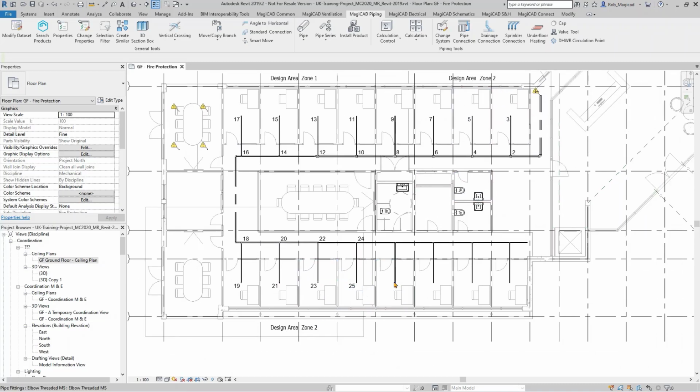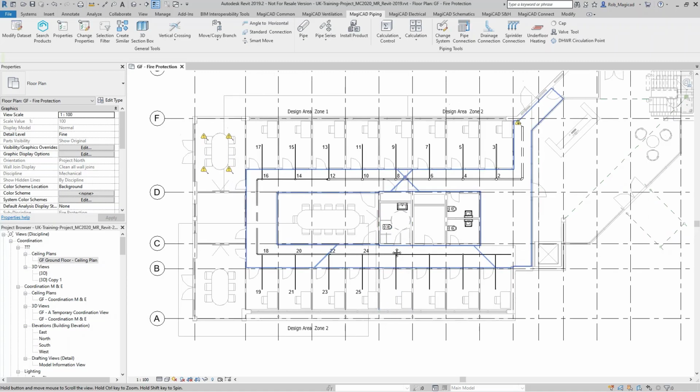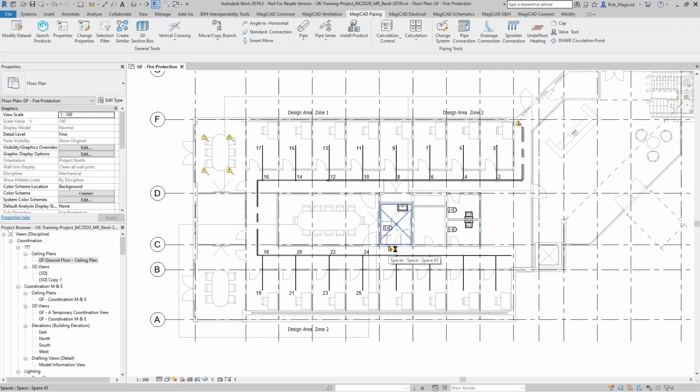If you have sprinklers that aren't contained in design areas, then the calculation ignores them. So you don't have to have an entire building with thousands of sprinklers being calculated at once. It would obviously be quite heavy to sift through all that data when you know that the likely weakest design areas are probably on the top floor, let's say, on a 10-story building, near the top floor towards the end or something like that. So you could just choose a couple of design areas in those worst case places and then review those.